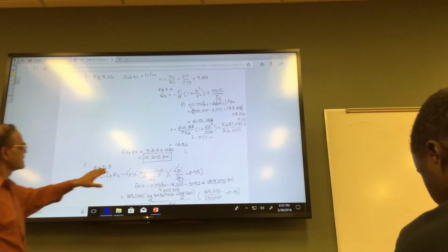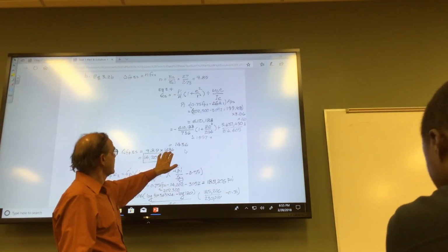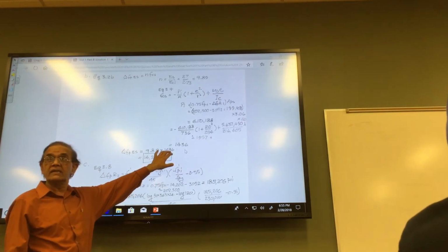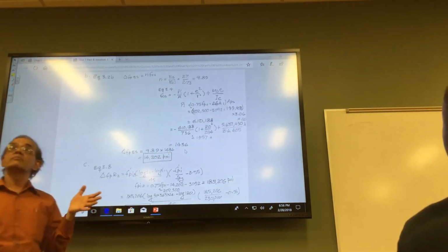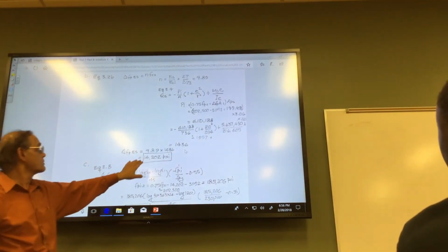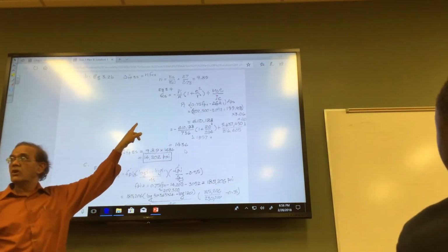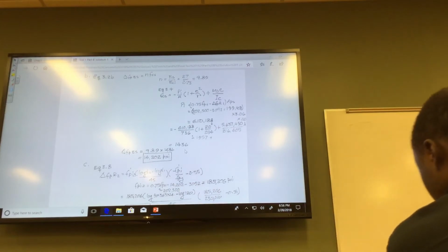The stress here is the stress at the center line of the strand in concrete, and this is the conversion, because there is strain compatibility: the strain in concrete is the same as the strain in steel. That's why you have to multiply by the ratio of the two moduli. That's the reason. Okay.